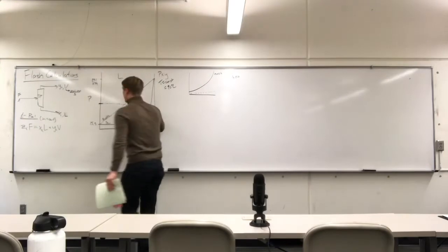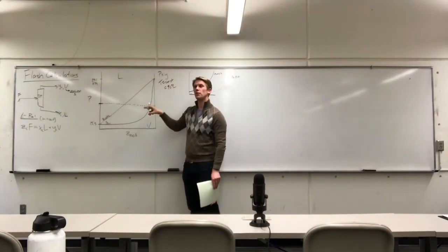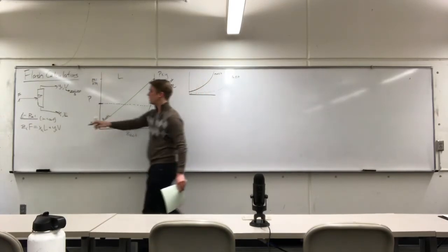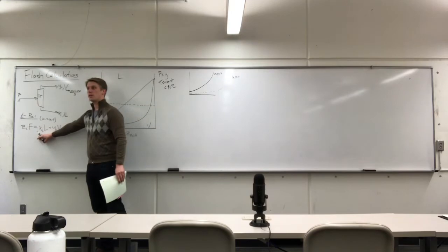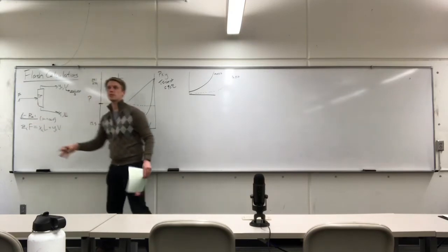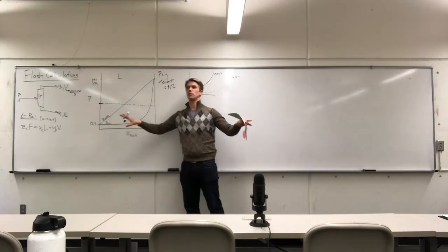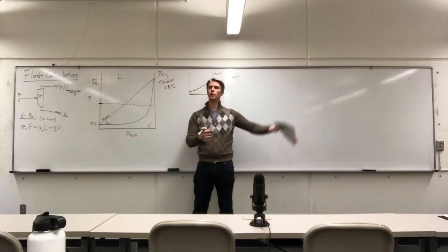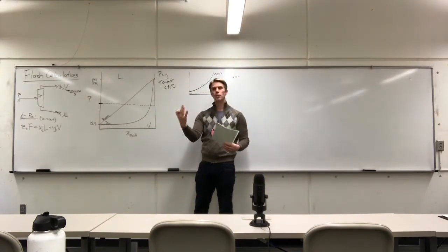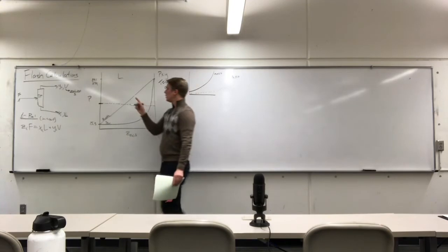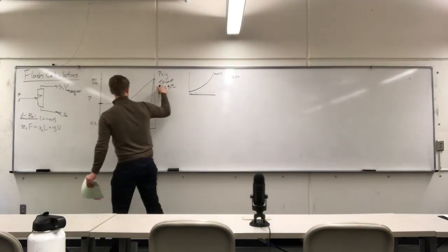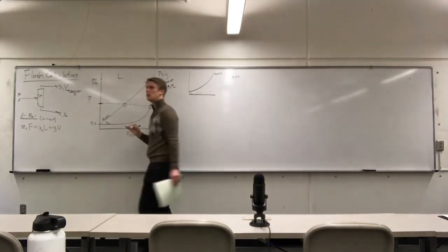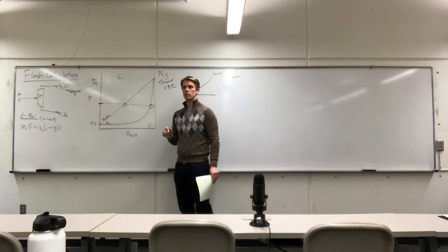Now, fluid phase equilibrium in thermodynamics, according to the Gibbs phase rule, doesn't tell us anything about the quantity of the phases. Material balances tell us about the quantity of the phases. Thermodynamics says they're just infinitely sized reservoirs. Right? I have an infinitely sized vapor reservoir with this composition. I have an infinitely sized liquid reservoir with this composition. They are in equilibrium. Thermodynamics helps us solve that problem. So if I have a fixed temperature, a fixed pressure, there are two solutions to Raoult's law, if this is an ideal scenario.